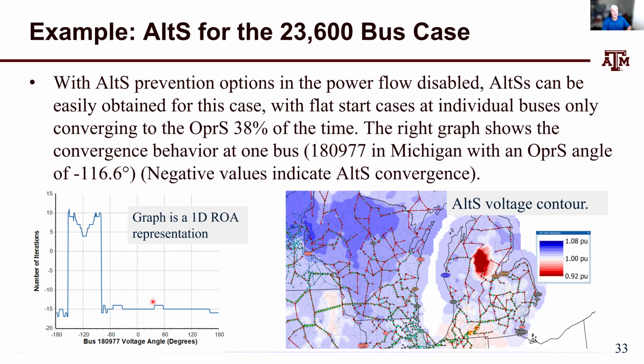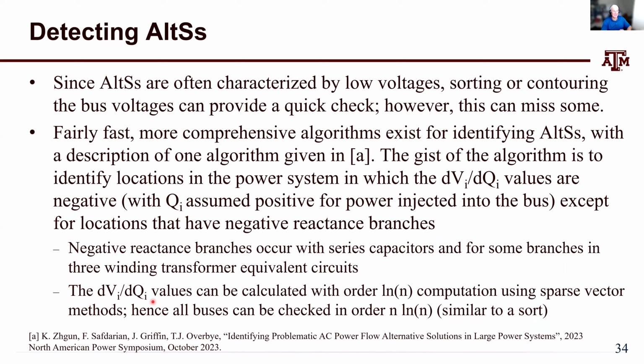So again, a takeaway message is if you're making an initial guess, maybe you're putting it into a script that you're loading up, try to guess an angle that is close to the angles of the buses that are going to be neighbors to the new one.